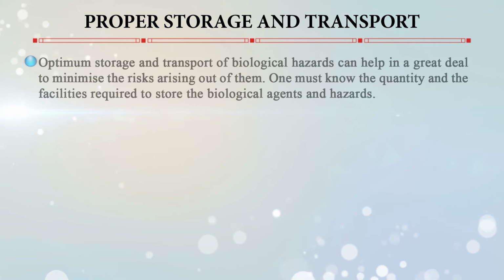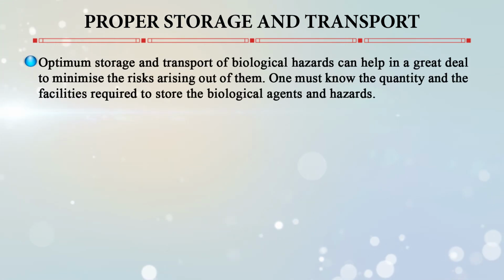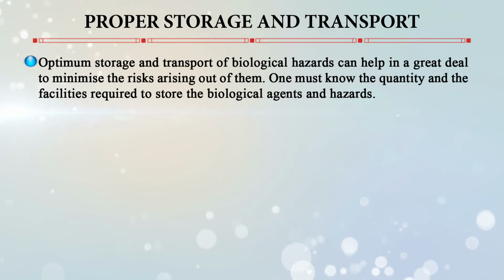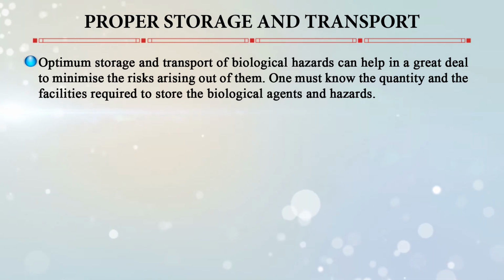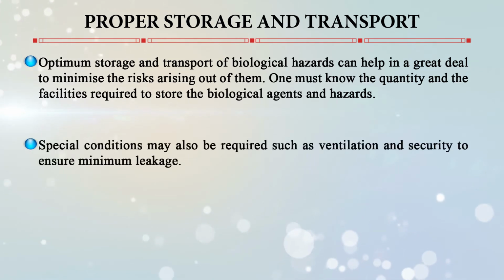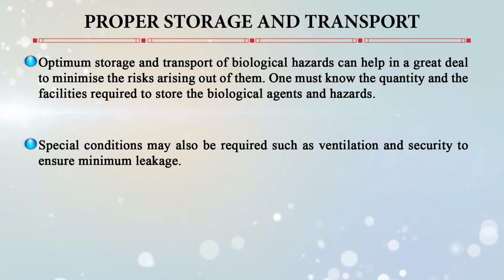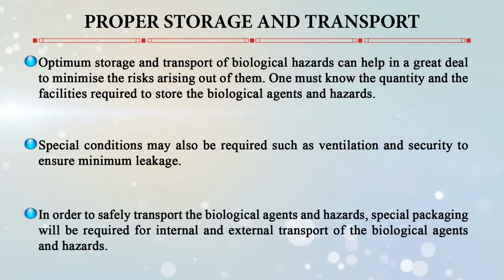The proper storage and transport of the biological hazards, so optimum storage and transport, can help a great deal to minimize the risk that can arise from them. One must know the quantity and the facilities that are required to store the biological agents and hazards. Special conditions may also be required, such as ventilation and security, to ensure minimum leakage from these agents. In order to safely transport the biological agents and hazards, special packaging will be required for the internal and external transport of the biological agents and hazards.